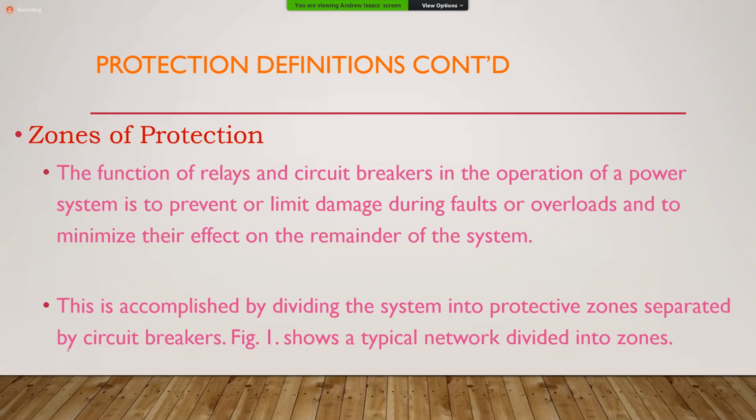So we said that a zone, a protection zone, is a piece of equipment. Yes. And I did say bounded by the relays that control the breakers. More simply put, it's just the piece of equipment, inclusive of the switch gear associated with it.